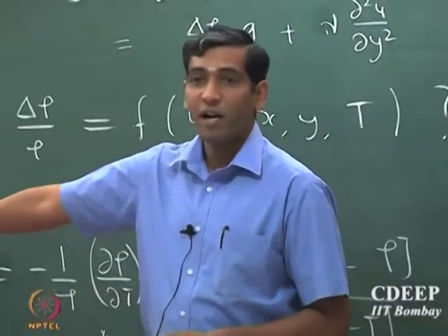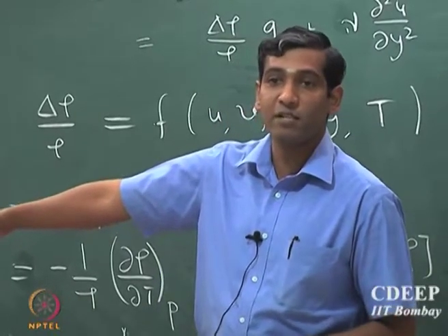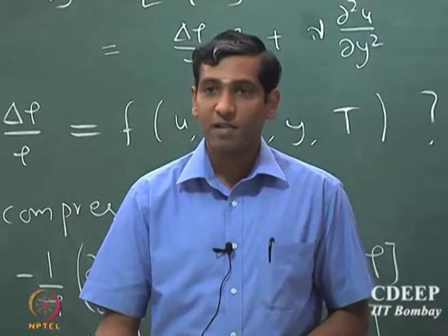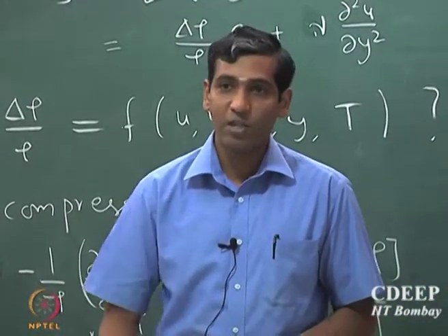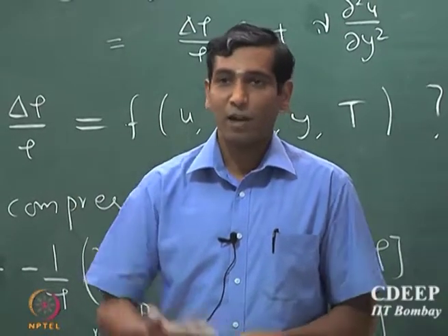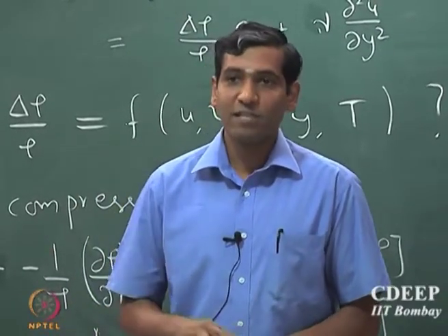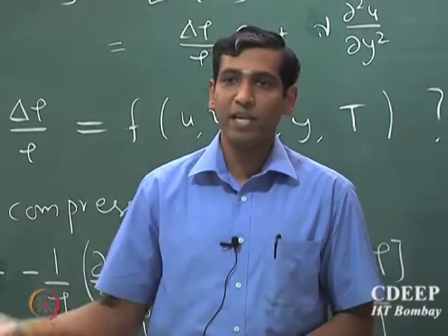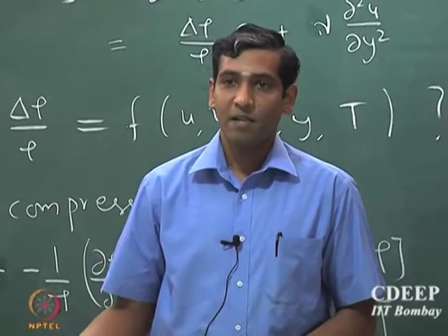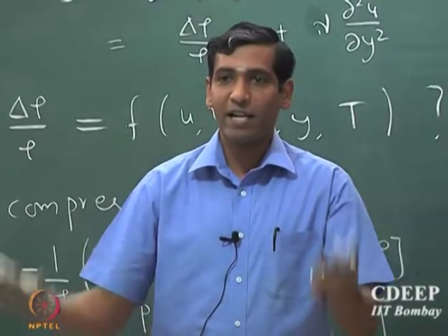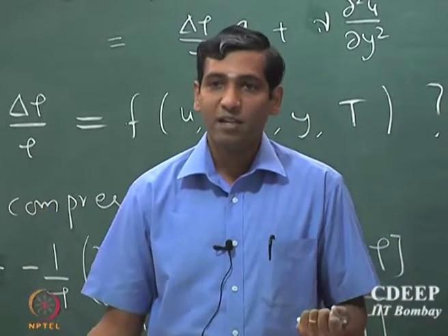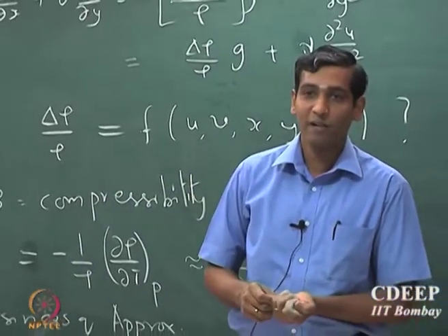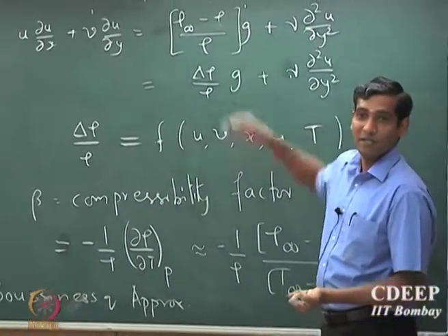That comes from the relationship between the pressure gradient in the quiescent region. If you write the momentum balance in the quiescent region, where there is no velocity, because the fluid is at rest, and the velocity gradient is 0, then you will see that the x momentum balance will simply reduce to the pressure gradient in the x direction being equal to minus rho infinity times gravity. And because there is no external forcing, the gradients have to be equal in the boundary layer and the quiescent region, and therefore you replace dp by dx with minus rho infinity into g, and that's how you get this expression.